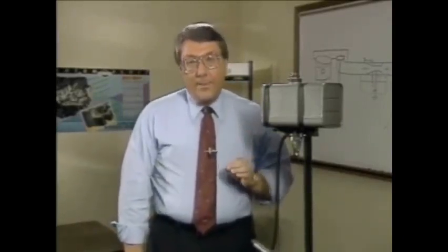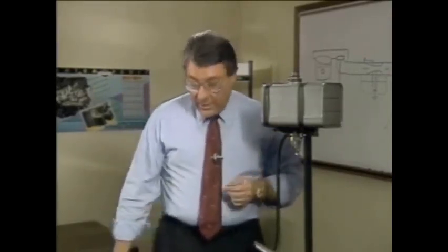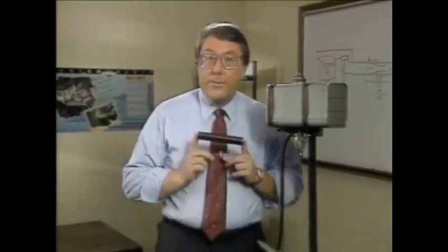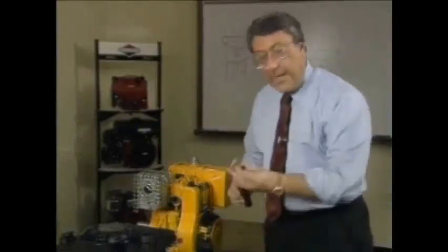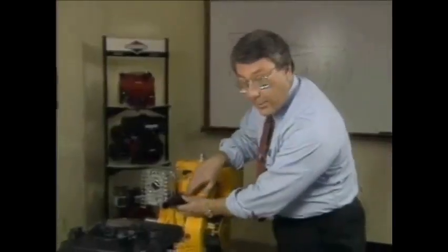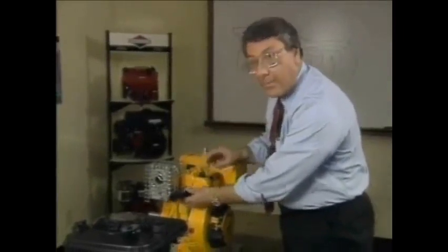Instead, let's build a carburation system that's more self-sufficient, that's capable of adjusting for changes in engine speed or load. To do this, we'll start with a simple tube. One end of the tube should have a flange that allows us to attach the tube to the engine. This is the beginning of our carburetor. The tube is used to direct the airflow into the intake port each time the piston moves down the cylinder with the intake valve open.